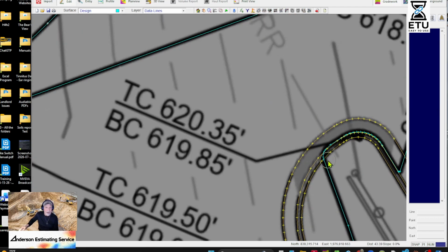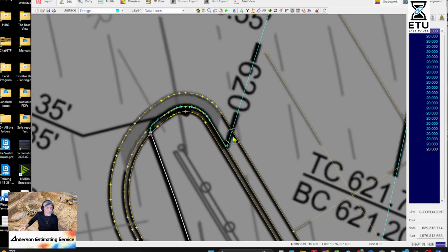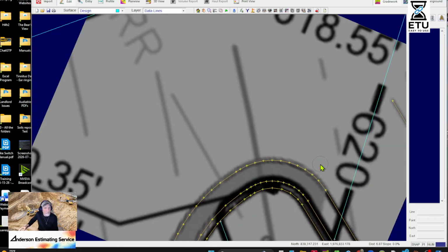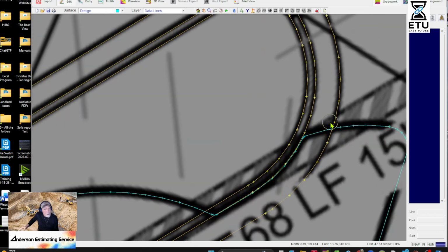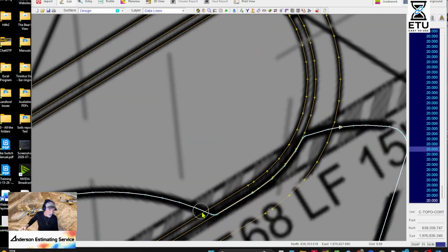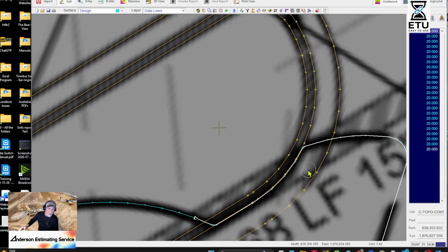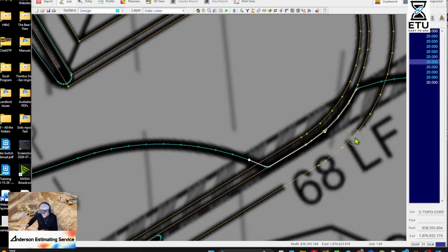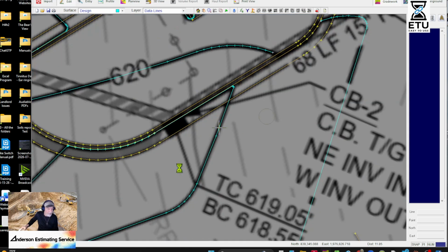They're just not right. See how all those contours are all wrong. They should run along that curb because the curb is just a half a foot retaining wall. It really is. So here, see how it's not supposed to do that. It's supposed to go running straight through that curb and hit that point. This is not the way this contour should be going. I have no idea why the AutoCAD somehow makes these files.